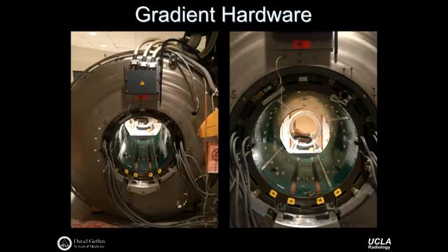If you look a little bit out in the distance here, this is actually the B1 coil. So you can just make out the table here. The B1 coil has been slid out. It would be concentric and inside of the gradient coil, and now it's just out on the bed itself. That's all the B1 hardware, if you will, that does the exciting. And if you look really carefully, you'll see these winding patterns on the inside of this gradient coil. You'll see just these curved lines, these pattern lines on both sides.